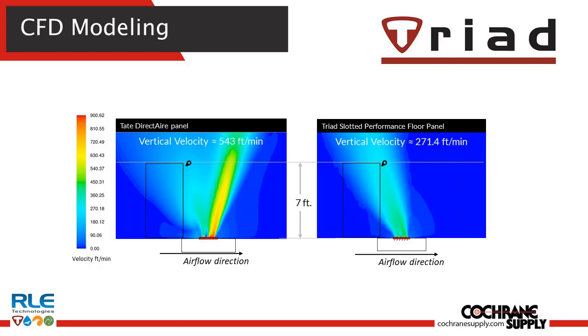So here might be another way to show the diagram, but ultimately when air gets pushed up from the underfloor up, the goal is to stratify that air into the data center cabinet so that it creates more effective and efficient cooling from 3 feet to 7 feet. If you're just pushing air up into the space, you're really wasting your energy because you're mixing hot air with cold air to cool the whole space, not directionally. What you're trying to cool is the data cabinet because of all those servers and the expense of the servers and the uptime requirements and all of that.